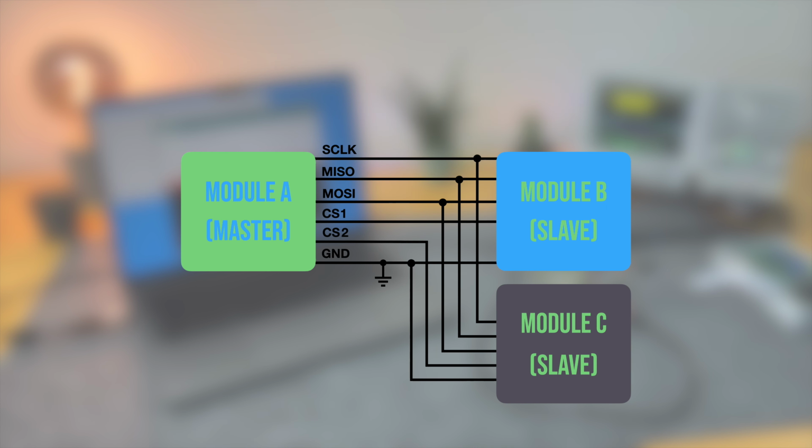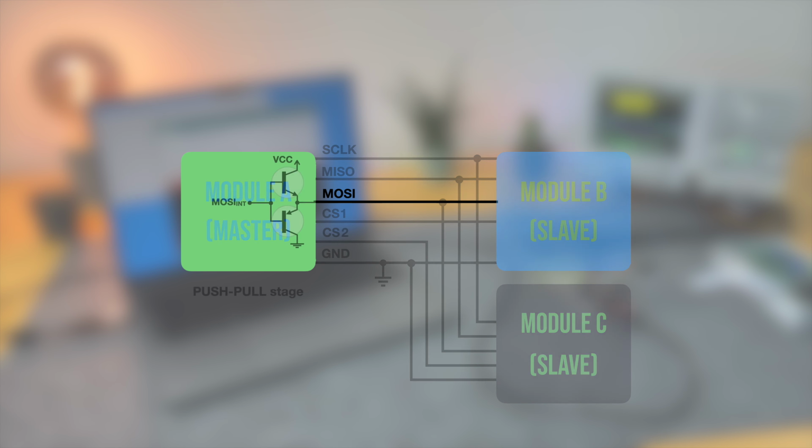This methodology is simple, but it's also very robust. In contrast to open drain drivers and pull-ups as used in I2C, SPI uses push-pull drivers, which enhance the load capacity and the switching speed, while also minimizing the power consumption of the circuit. Thus, SPI can typically be used with much higher speeds of multiple megahertz.